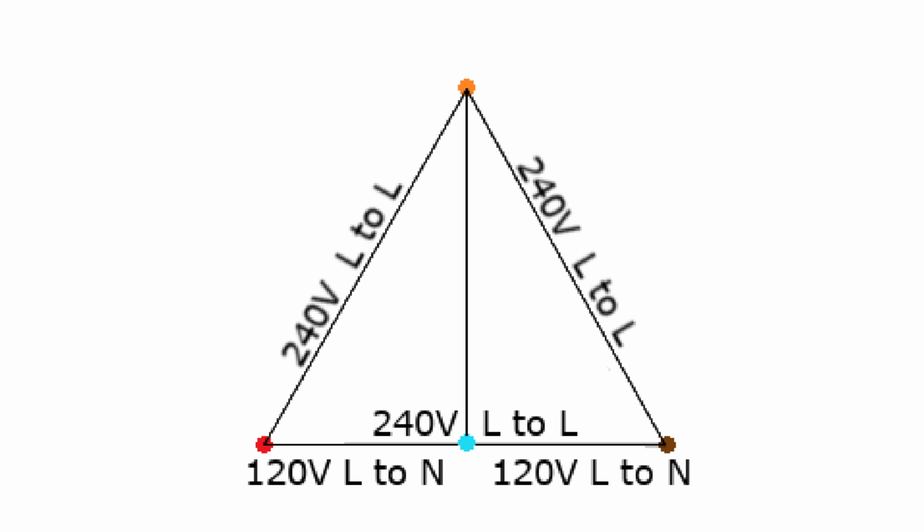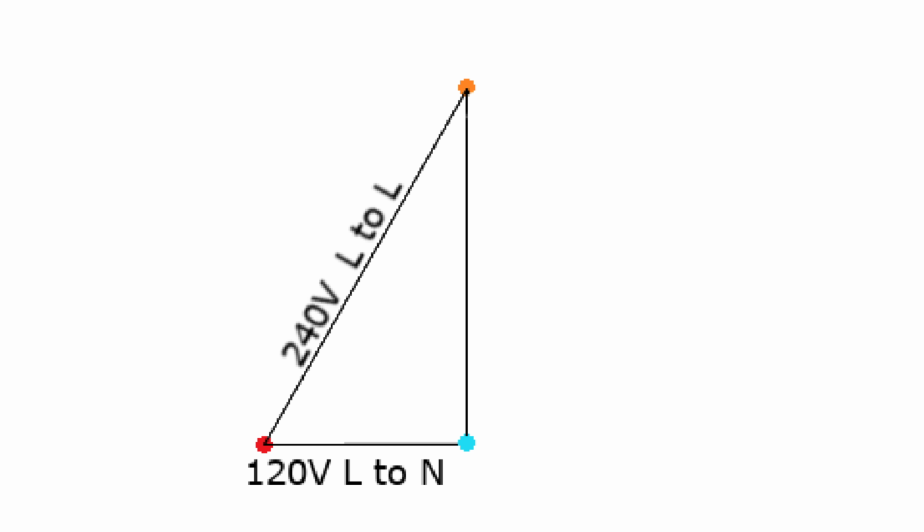Let's explore what is actually happening in these voltages and see if we can figure out what the voltage from the third phase to neutral would be. For a minute here, let's just look at the red wire, the neutral, and the high leg, and let's forget about the rest of the triangle. Let's think about this for a few minutes in terms of voltage from the red phase. The neutral is 120 volts from the red phase, and the orange phase is 240 volts from the red phase.